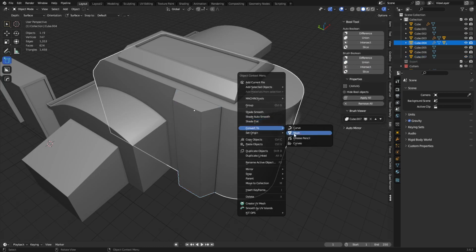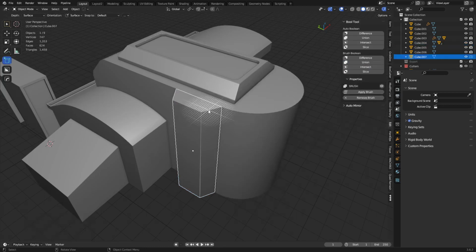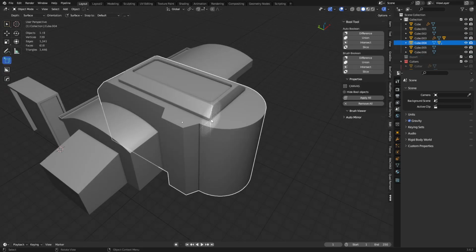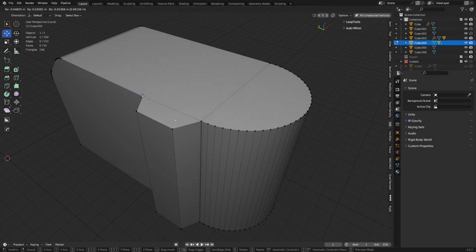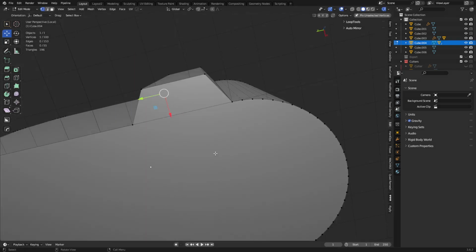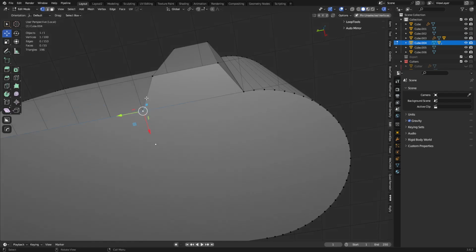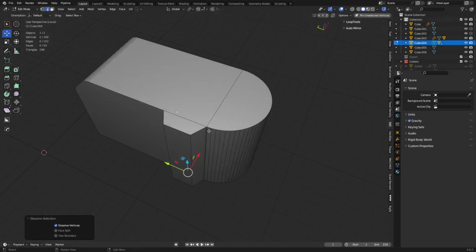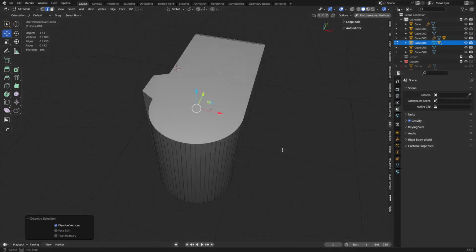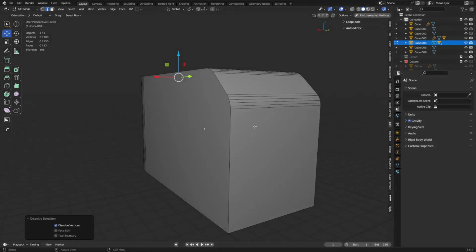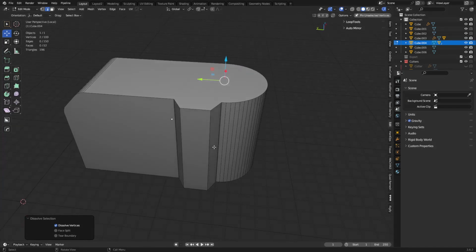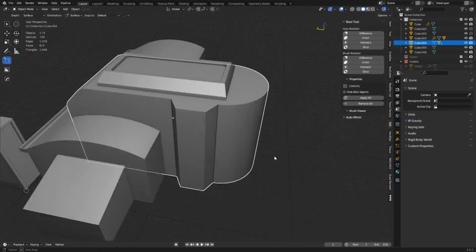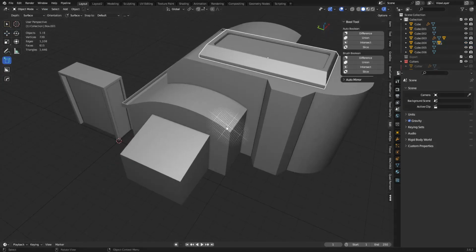If I was to convert this to a mesh, the main shape there, and delete the little piece we had created there, a lot of times we have just a perfect little setup now. There might be some errors in it. You might have some here at the bottom, but this one actually worked out just fine. There's nothing here to fix really. We could dissolve that if we wanted, and go back to optimizing it to a very basic Boolean model. But yeah, you see, you can combine shapes very fast with that exact solver.